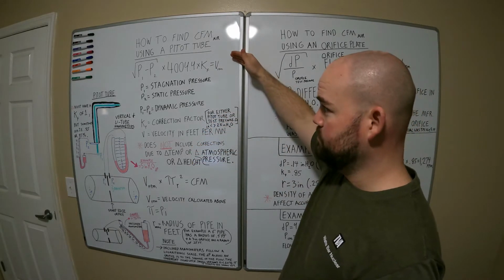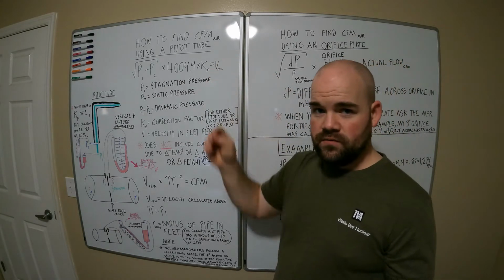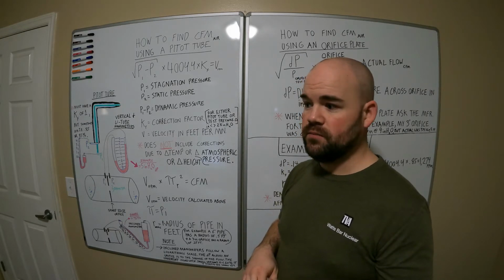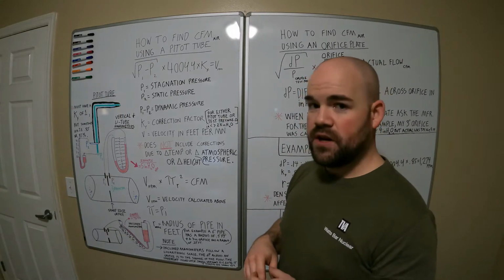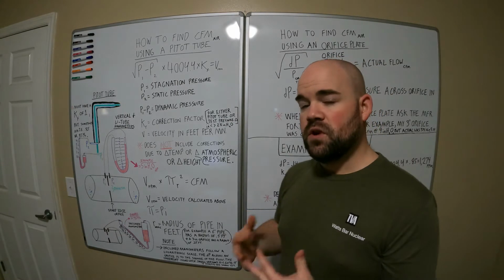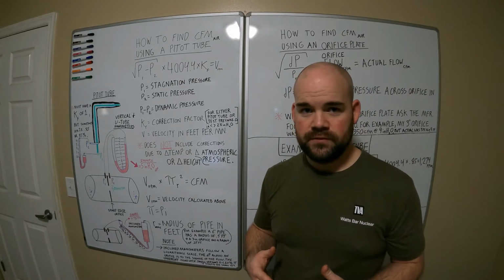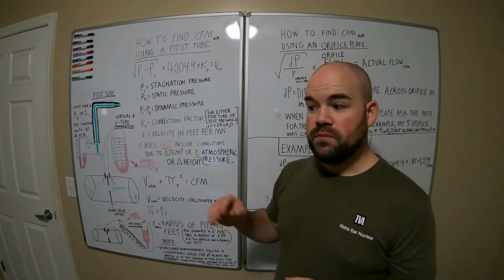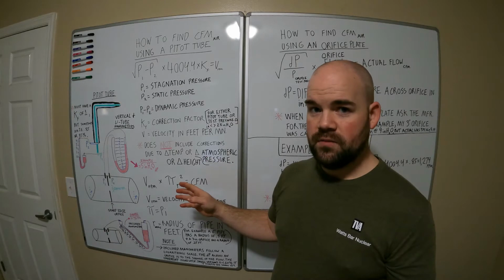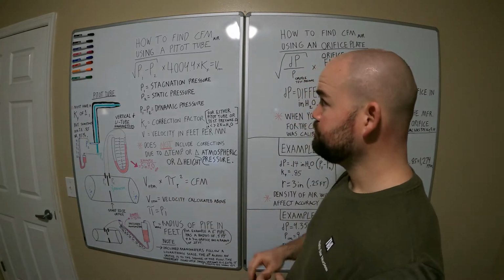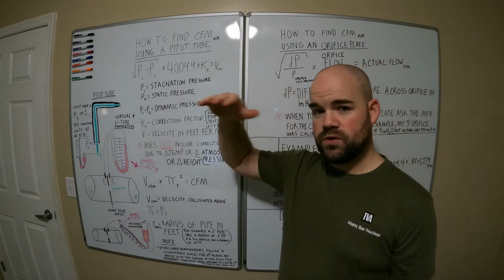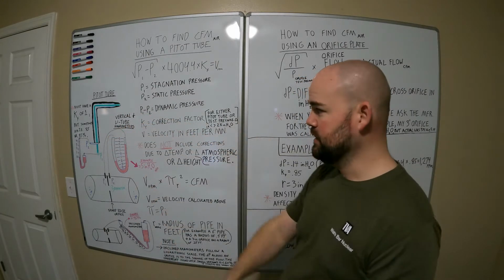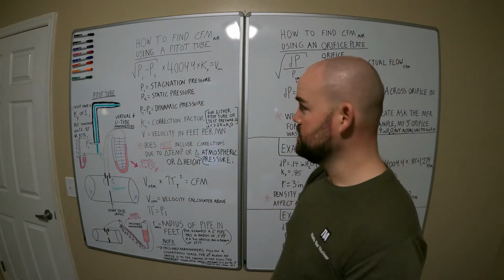So a pitot tube, okay, it's used in Formula One racing, in aircraft, in anything that needs to know airspeed, pipes, HVAC, they use them to measure airspeed. So it's all airspeed. If you know how fast the air is moving, okay, and you know how dense it is, okay, that's key, density, you can measure CFM if you know the diameter of the duct, okay? So what we're going to talk about is a horizontal duct, okay? No change in height, nothing like that, just a horizontal duct, which is how my bench works, okay?